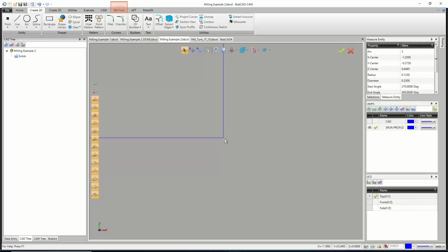So I'll delete it. Again, to double check it, grab select tool, hold shift, click, make sure the chain goes all the way around, then check it from another spot. So I'm clicking it, still holding shift down, clicking it again to turn it off, and going to a different line and clicking that. The reason I check two sides is because when you send a chain in BobCAD, when you hold shift and click on something, it actually sends the chain in one direction.